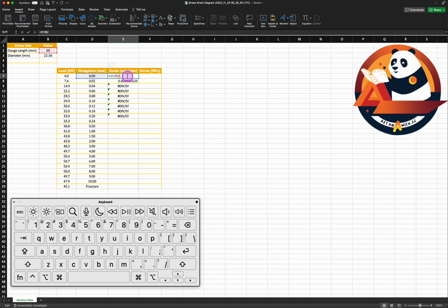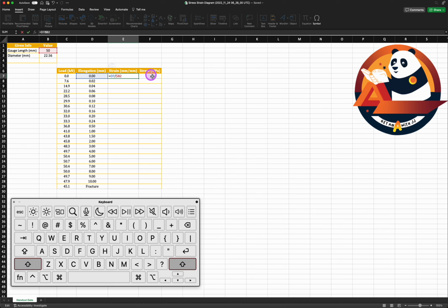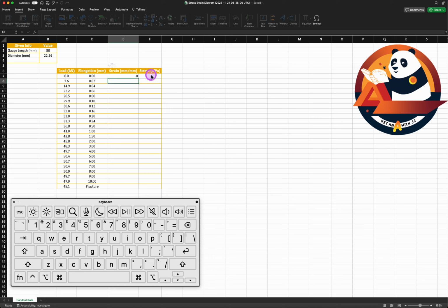Without any reference in here, Excel's just going to update. If I go down one cell, it will still reference 1 to the left and 8 or 9 over. I want it to always reference this 50 millimeters though, so I don't want to do just dragging it down. I always want to reference one cell to the left. So I'm going to leave that D7 as is, but I want to always get that B52, 50 millimeters in there. So we can put dollar signs in front of the B and in front of the 2.